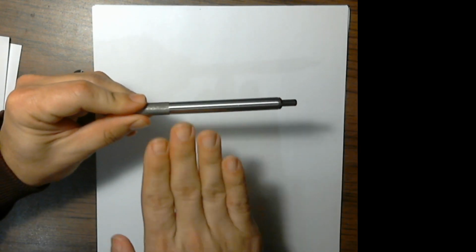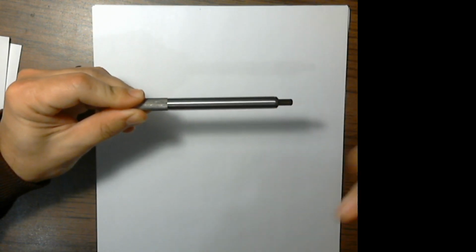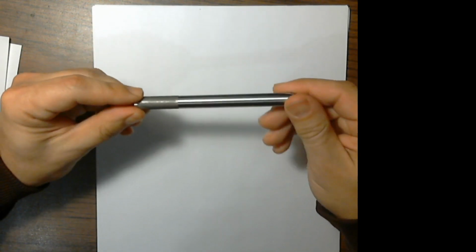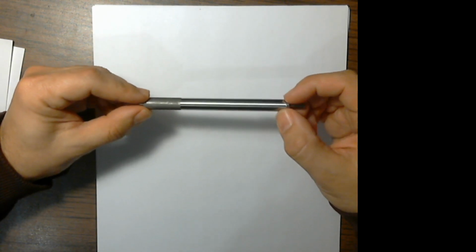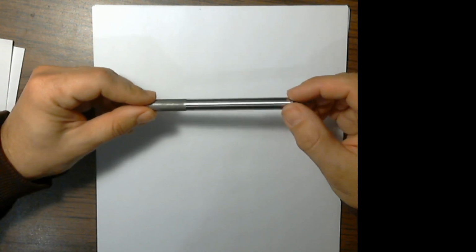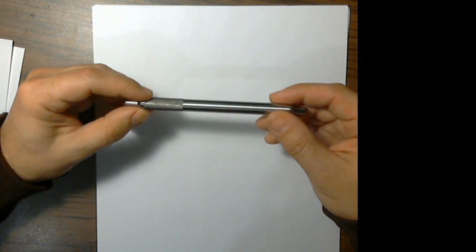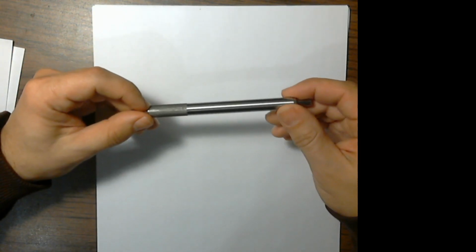The faster the airflow goes over the wire, the better job the air does of wicking away heat from the wire. You can use this with nothing more than a chunk of metal in a tube to figure out what the airflow rate through there is. This is not a terribly precise method. It's not terribly accurate, but it works pretty well actually, and it's pretty robust, which is one of the reasons the automotive industry likes it.